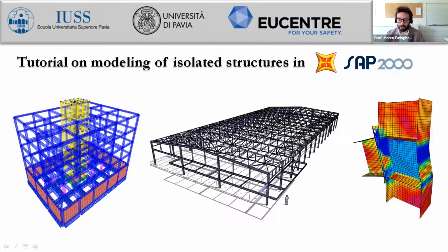So this means that between this plate and the flange of the column, you should also place some gap elements. And gap elements, even though the overall structure may be linearly modeled, are highly nonlinear, because you just model for compression when the gap is closed, and whenever it opens, there is automatically the detachment of the two surfaces, and so there is no response. So this is nonlinear.